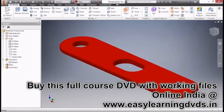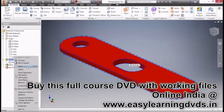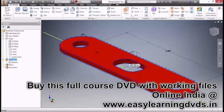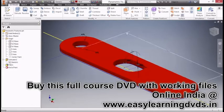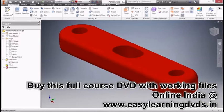Just to check how that works, let's go back and use Show Dimensions on our extrusion by right-clicking on it. And here, we'll change this from 0.125 to 0.5, much thicker. I'll go ahead and update this. And you can see the fillets maintain a size that is in relationship to that overall thickness value.